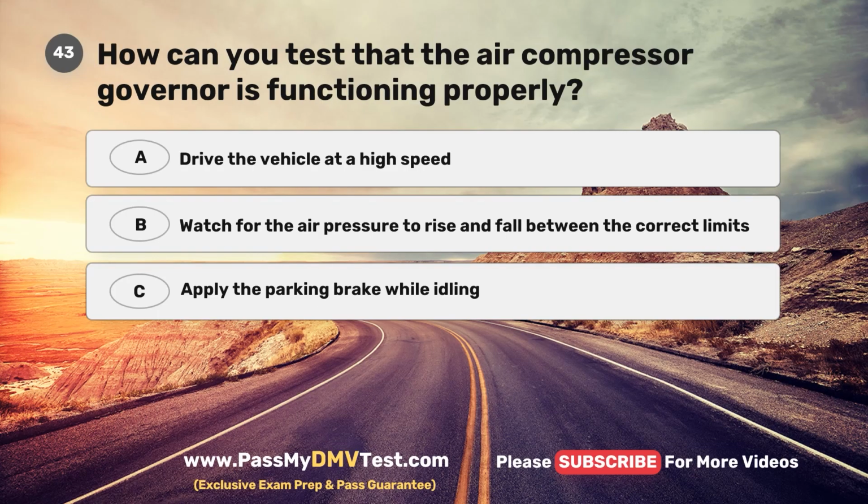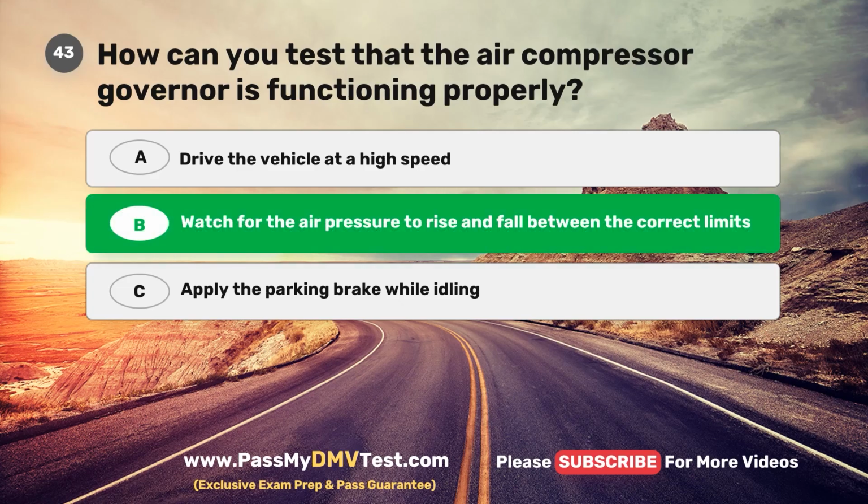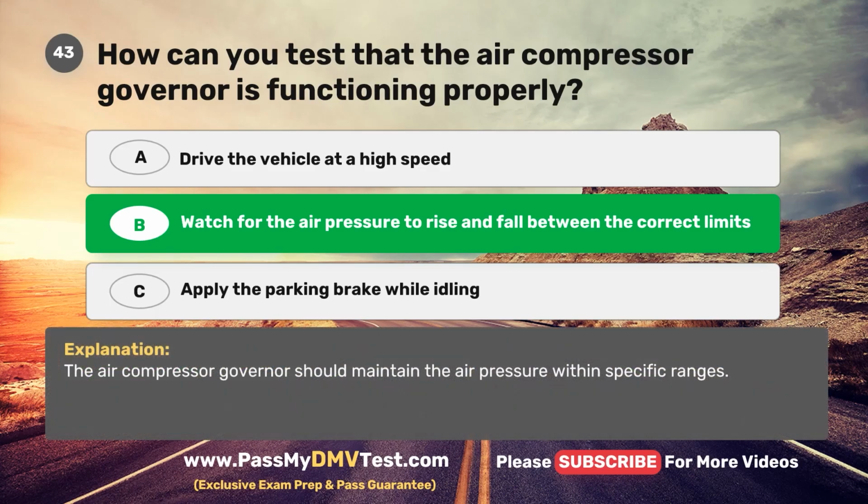Question 43. How can you test that the air compressor governor is functioning properly? A. Drive the vehicle at a high speed. B. Watch for the air pressure to rise and fall between the correct limits. C. Apply the parking brake while idling. The correct answer is B. Watch for the air pressure to rise and fall between the correct limits. The air compressor governor should maintain the air pressure within specific ranges.